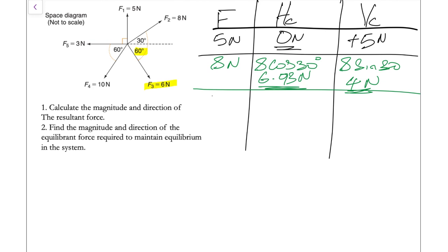So our force, 6 newtons, and we're going to keep the same system, but this time around be mindful that this force is going down and it's going to the right. So for the horizontal component, it will still be a positive 6 cos 60, and when we put that in the calculator, cos 60 again is 0.5, so therefore this is 3 newtons.